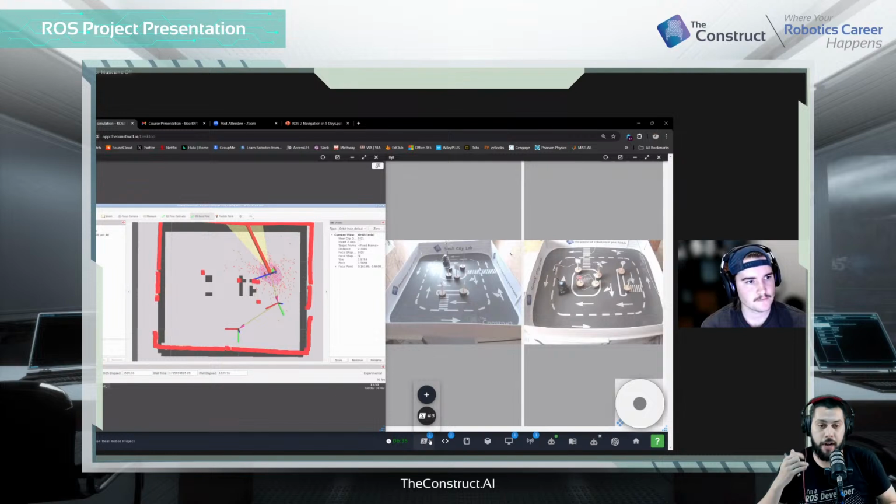For example, AMCL is publishing map to odom, and then the robot state publisher is publishing from odom to your base footprint. So that's the actual reason why you probably won't experience this unless you're working with remote applications. I just wanted to mention that to have it clear.